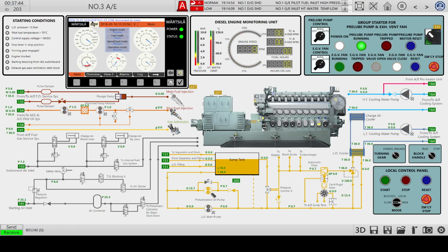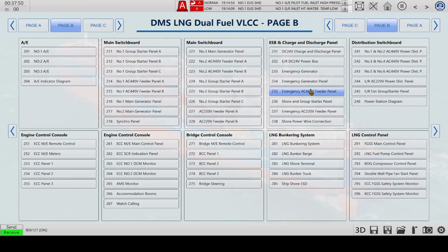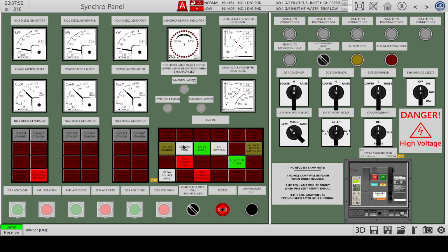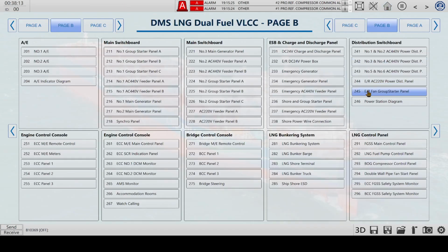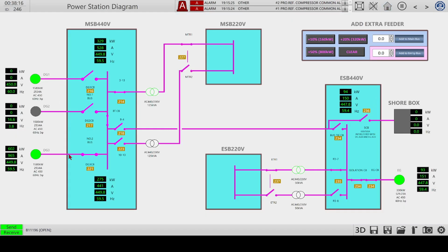And what is the excuse for number 3? It is in standby, so why didn't it take over when the first one stopped? Because we're not in auto mode. So now the third one is on standby. And you see the third one actually started. Two generators running. Third, even this one is going online now, because the breakers of these two are not closed.